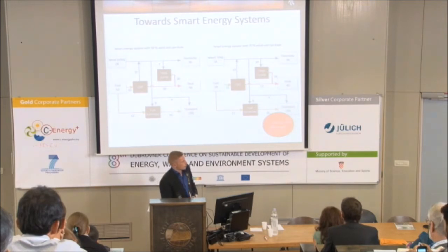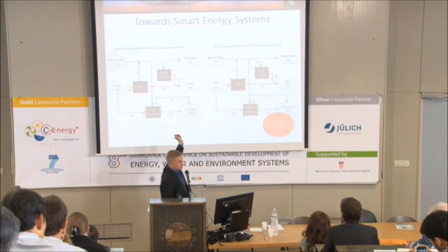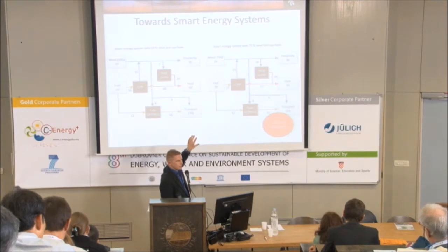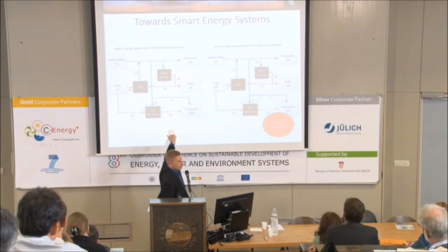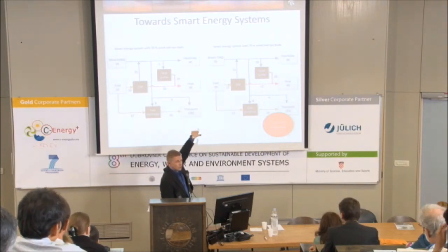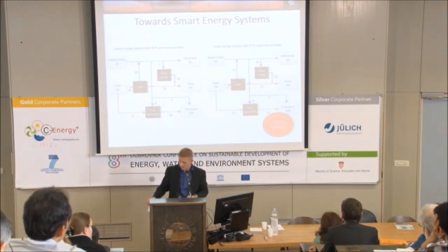I don't know if you remember before, with the second generation biofuel, it was 80, the fuel input over here. But the characteristics of this system means that we can actually increase the wind power penetration. So now we can go from 50% to 75% or even more, but in this principal diagram we have 75%. And by doing so we can come down to a fuel consumption of maybe 40 in this principal diagram.